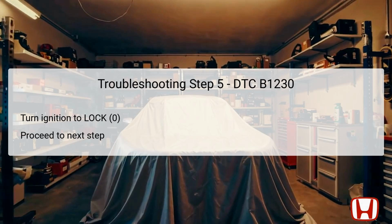Once the ignition has been switched off, technicians can safely proceed to disconnect the sunlight sensor and climate control unit connectors for further diagnosis. Ensuring the ignition is in the off position forms part of standard safety protocols during vehicle diagnostics and repair. In this step, the technician must disconnect the 5P connector from the sunlight sensor. This action allows direct access to the sensor's wiring, which is crucial for further testing.